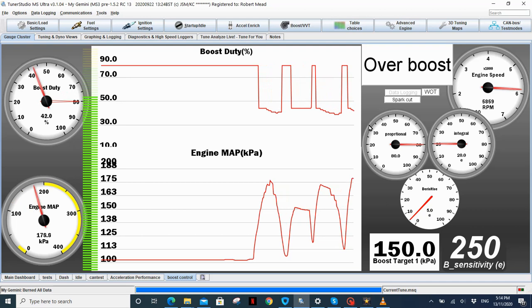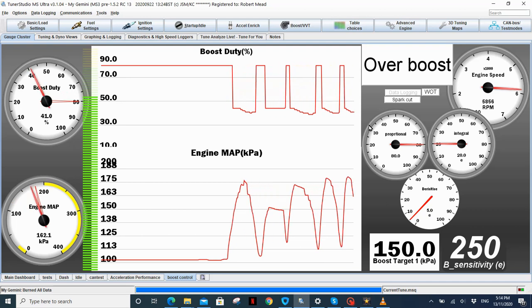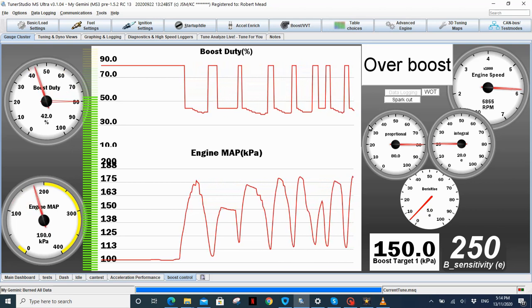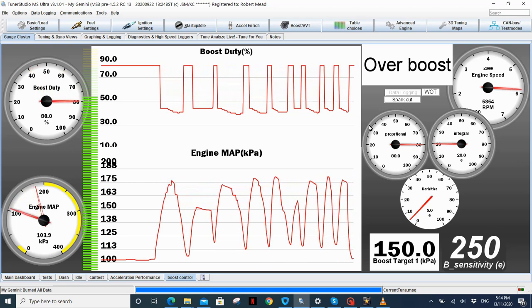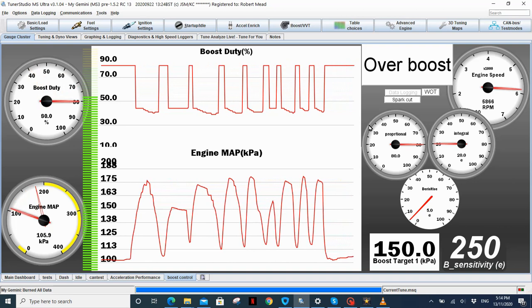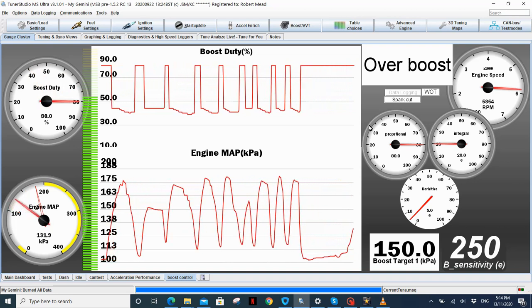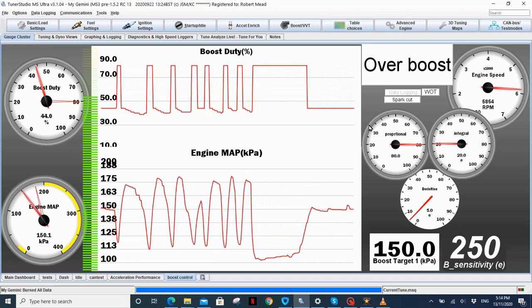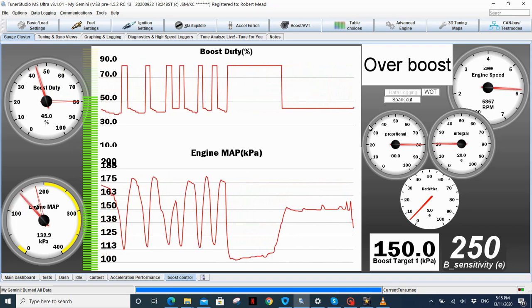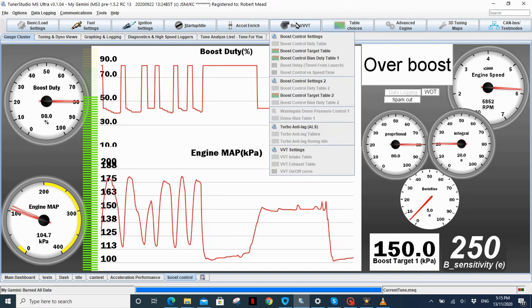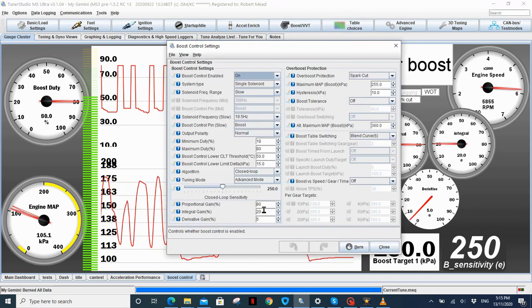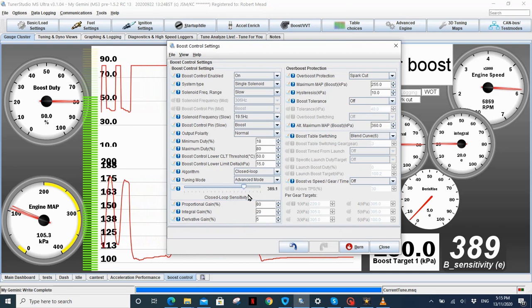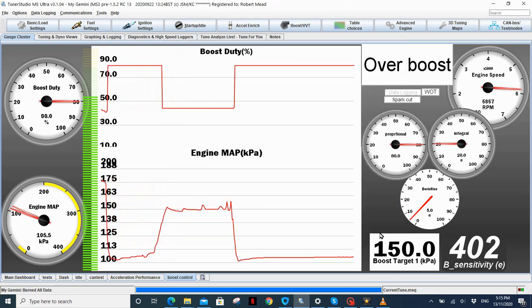Really, that's nowhere near. That's heavily over boosting. That's not really reacting as much as you want it to, but if you've got your bias table set up, then what it should do is shoot up pretty much to your level there. And you can see it's not really reacting to those changes, so you probably want to have a bit more in there. We could turn up the sensitivity, or we could just turn up those numbers as well, which would sort of do the same thing.